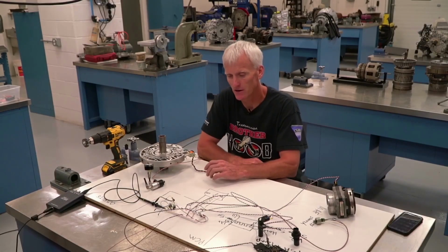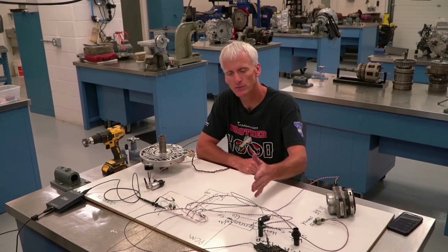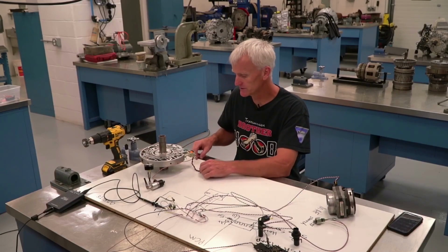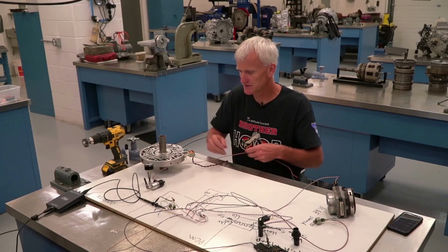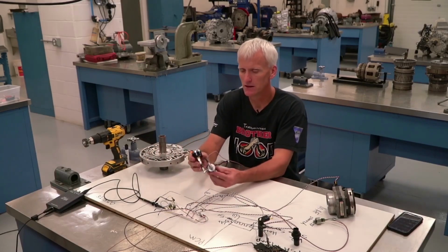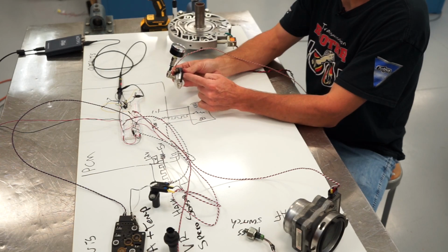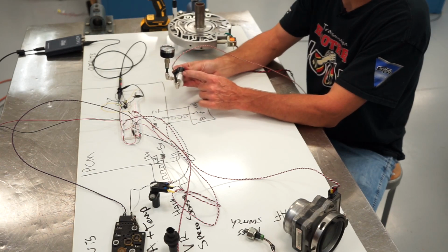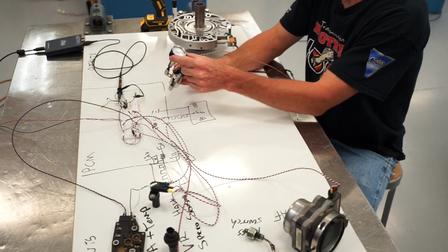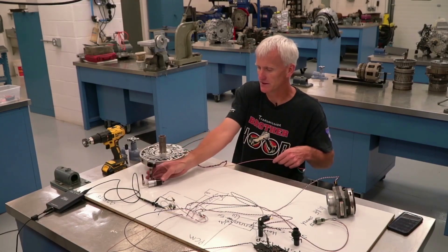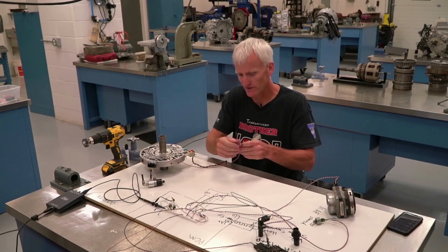When we look at outputs on automatic transmissions, we're basically dealing with solenoids. We use all this input information so that the computer can decide how to control some solenoids. And I've got a couple solenoids here as an example. This is a solenoid out of a Mercedes, and it's a pulse width modulated solenoid. So fluid is actually going to enter in through the bottom, and based off of how this solenoid is operating, it's going to come out and operate a clutch circuit. And I put a pressure gauge on here, and we're going to try to control this. It's not the easiest thing to do without more advanced circuitry.